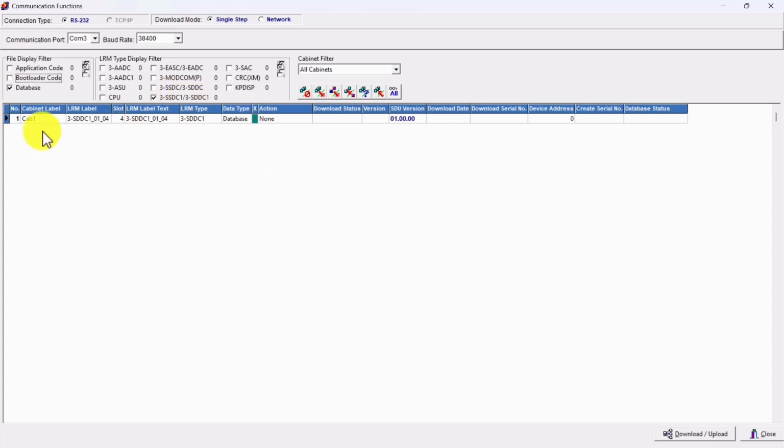So any changes you make to the fire alarm system, if you add a device, if you change the character from lowercase to uppercase, you have to download the loop controller, and you also have to download the CPU. Both these cards need to understand what the changes are. Now, if you're just working on a map fault and you just changed out the same device with a new device, then the CPU doesn't need to know. Only the loop controller needs to know at that point.